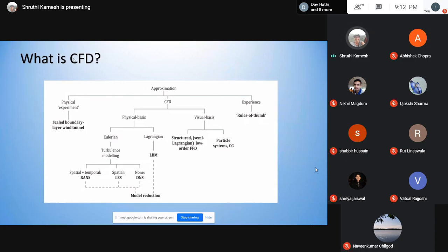The main fluctuating part is the turbulence part. And that is what people use several turbulence models to converge. So when they say they want to solve the RANS equations, they would always say that I'm solving the RANS equations a particular way, and what your turbulence model is. Now, the turbulence model is used to essentially model what is called the Reynolds stress term, which is a very key thing in visualizing the turbulence in the flow. Turbulence is basically inherent uncertainty.